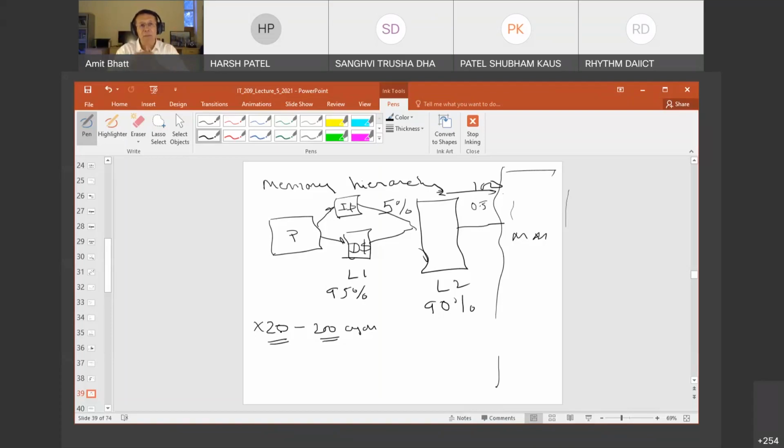So as soon as there is an impact, a sensor, basically an accelerometer, detects it. So your car is going fast and suddenly it decelerates to 0. So that means the sensor would send a signal, and the signal would be sent to two chemicals. They are filled in two pouches, and the pouches break, and the two chemicals get together, and that creates an instant reaction, and it blows up, and it creates gases, and that would instantly inflate the airbag. So that is how the airbag operation takes place.